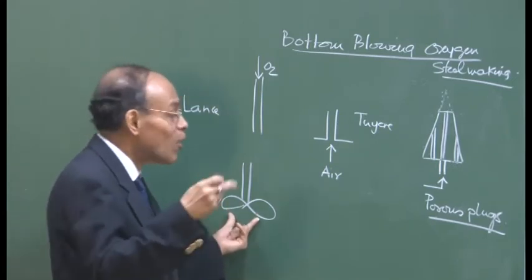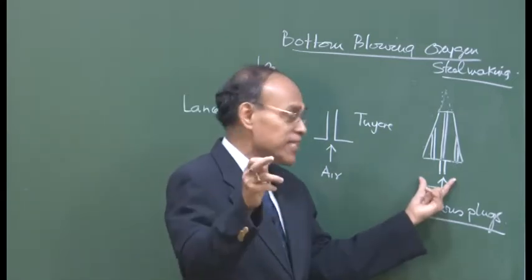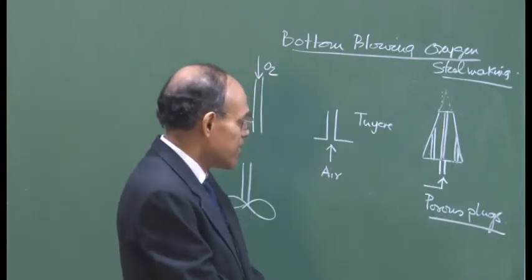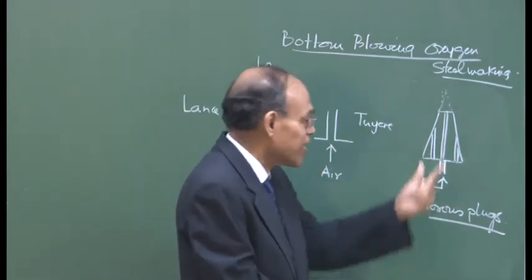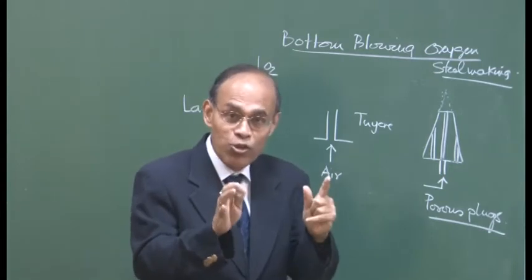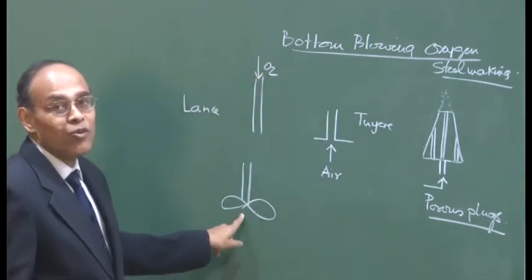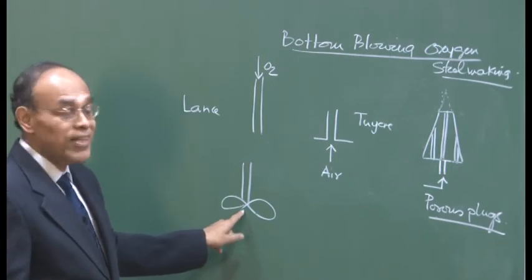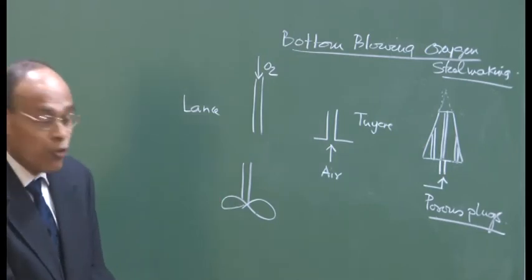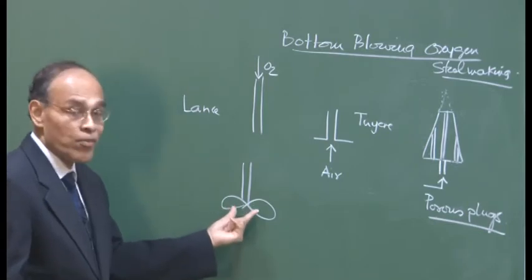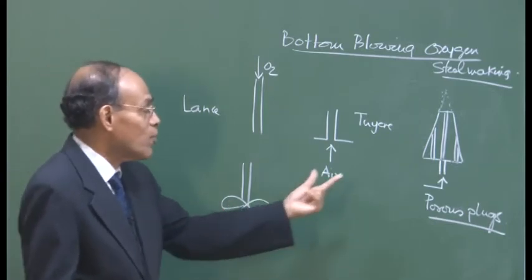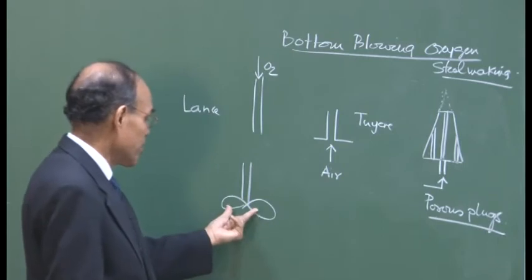The simple fact is that gases, particularly inert gases, we will see in secondary steel making or ladle metallurgy, when you blow inert gases and take extra precaution not to contaminate molten metal, even though impeller stirring could be economically more advantageous. Material consumption is low, as you require only a porous plug. Porous plugs are far cheaper than these impellers.